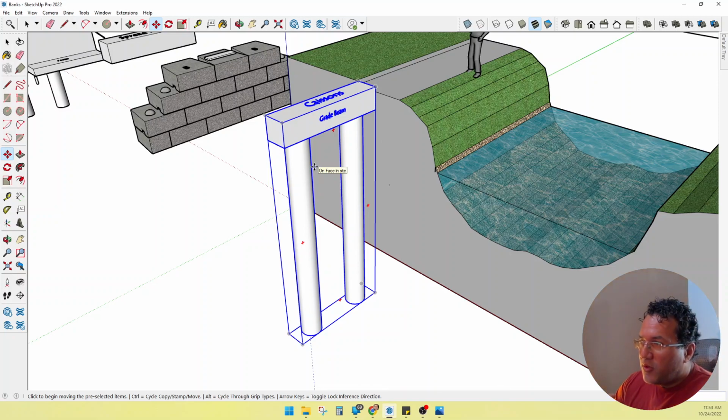You have to drill holes in the ground, and then you hope that your soils don't fall in. It's called sloughing off. The soils will slough off inside the hole. Then you have to pull that out. Then, if you start getting water inside the holes, you have to get a pump to constantly pump the water out while you're trying to pour concrete in. Even after you get the holes dug, you have to have an inspector go out there to verify the holes. Then you have to have rebar set in these, and this is not something you can do by hand. You have to have a crane on hand just to set the rebar cage inside these holes.